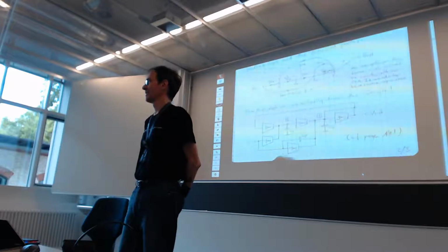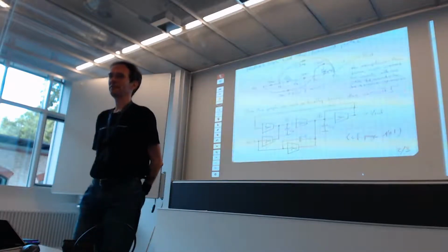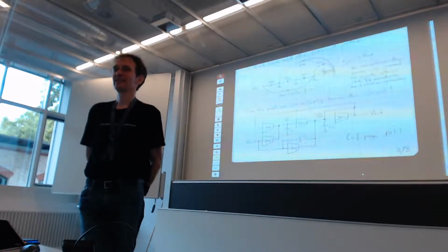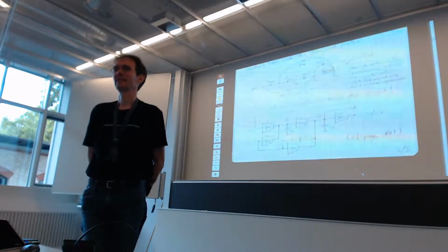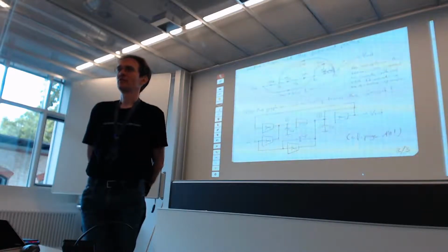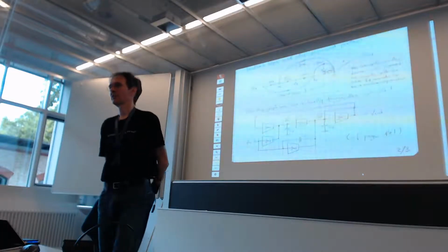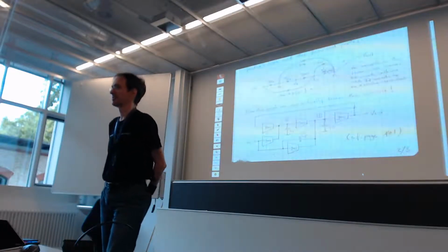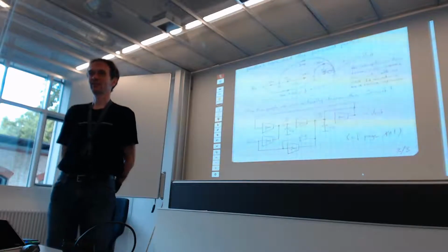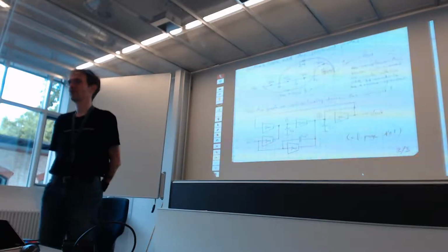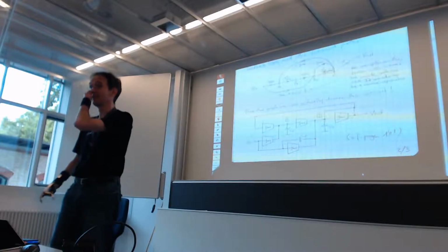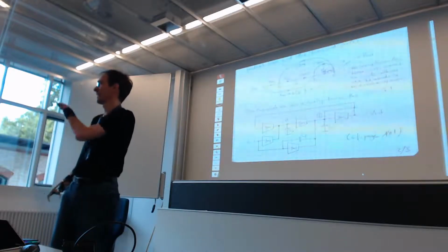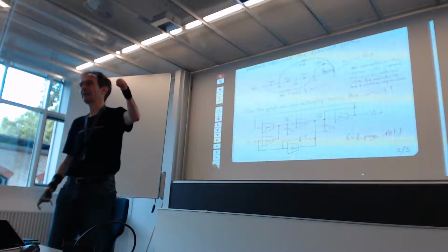In the lecture after the signal flow graph break, I will show you how to calculate how much power a transconductor needs. But for me, as an experienced microelectronics engineer, if I hear you want a GM of 1 Siemens, that would mean that if you have 1 volt, which is reasonable on an IC, the output is 1 ampere. 1 ampere?